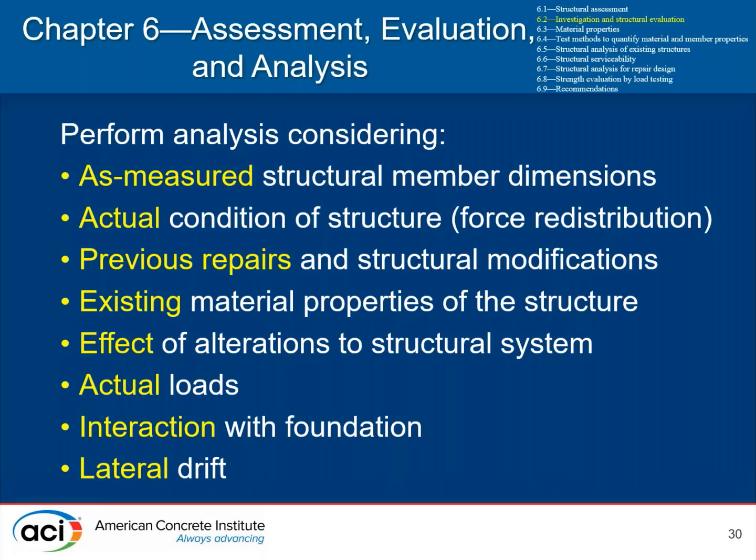that there haven't been conditions that have changed, or there weren't original construction defects that can impact either the strength of the existing structure or the methodology or strength of the repaired structure once that's conducted. Evaluating the actual condition of the structure, including force redistribution that might occur from either the deterioration or the repairs. And we'll talk a little bit more during this presentation, for instance, about external post-tensioning or original post-tensioning of the structure.